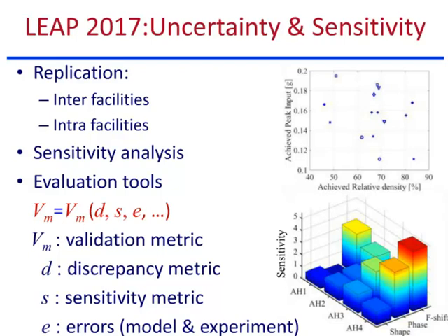So we conducted more centrifuge tests. Now we have about 16 replicas of the same tests that were done at different facilities in June and July of 2017. The idea here is to cover a range of variations in input motions and soil relative density to assess the sensitivity of soil response to variations in soil parameters. Whatever precautions we take in centrifuge testing, we will never be able to replicate the test in a realistic fashion.